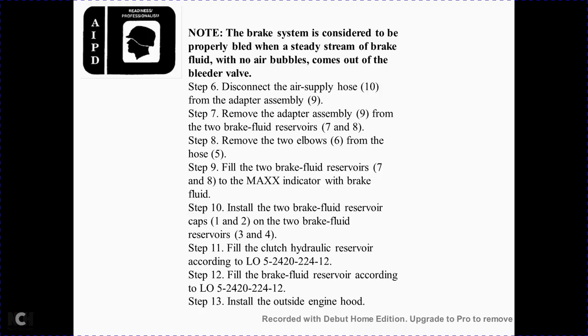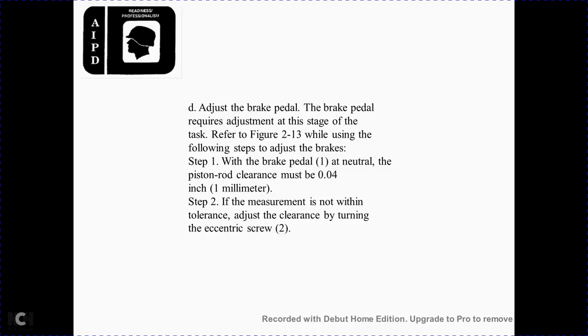Step 11, fill the clutch hydraulic reservoir according to lubrication order 52420222412. Step 12, fill the brake fluid reservoir according to lubrication order 52420222412. Install the outside engine gauge. Step 13, adjust the brake pedal; see brake pedal readjustment in the next task. Refer to figure 214 for the following steps.